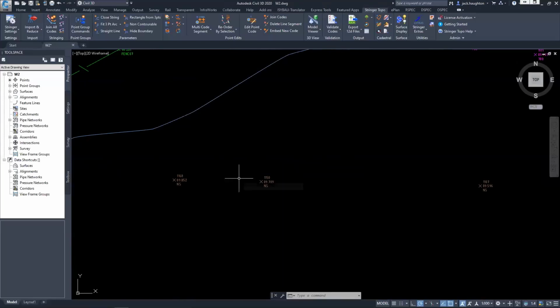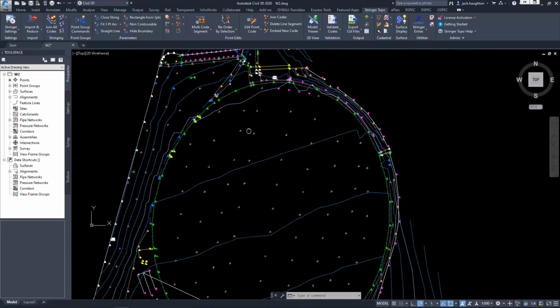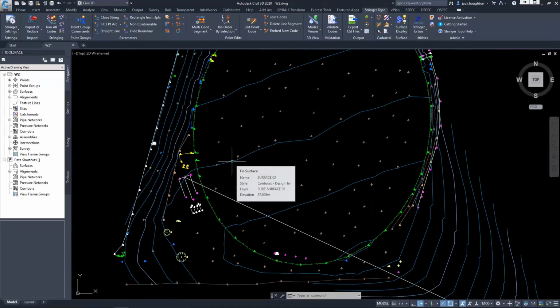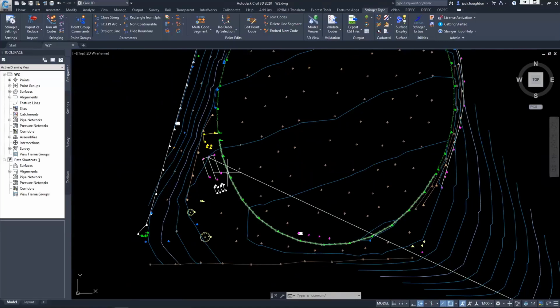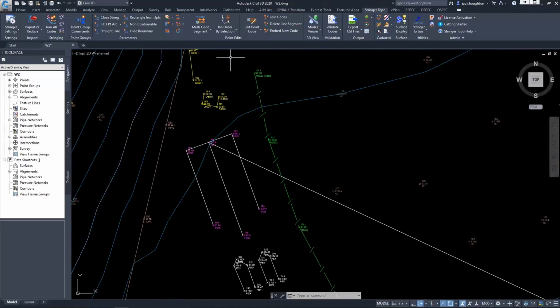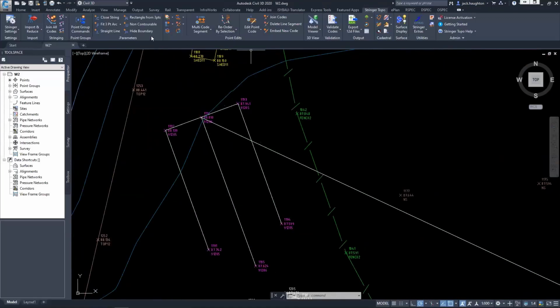So what if you've gone through, you've done your survey, you want to look at the traverse you've done, but you don't want to look at every single line. You just want to go, okay, I just want to see everything that I've traversed so far. We've actually got a little command which isn't too well known. Not a lot of people seem to use it, but if we run ls trav,